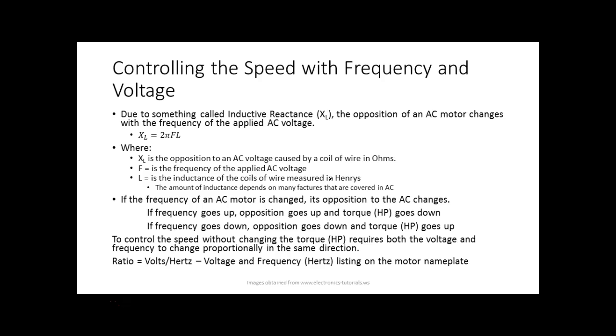So we do that. We don't ever run the motor above its rated frequency. And you have to get the thing running. But what's nice about an AC motor variable speed drive is you can set an acceleration on that thing. So it'll actually bring that thing up to speed instead of just trying to start it up with full power. So variable speed drives are really neat.